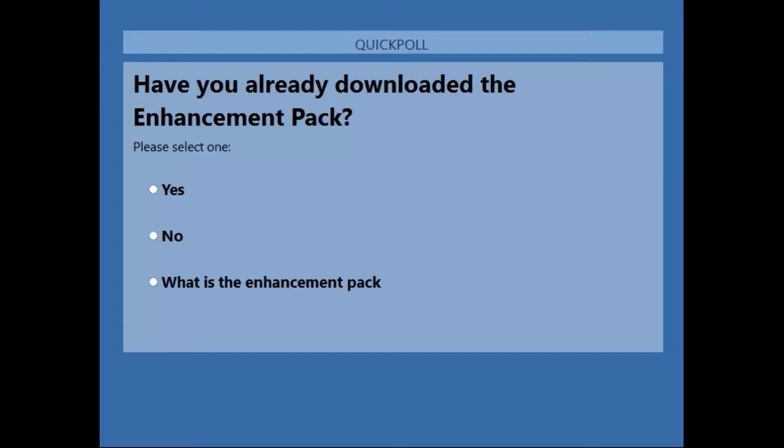When you install the enhancement pack, these subassemblies are stored in C, program data, Autodesk, C3D 2017, ENU, V1 enhancement subassemblies, and then Imperial. There are also the subassemblies for metric. So this is a list of all of the subassemblies that are available in the first enhancement they've released.